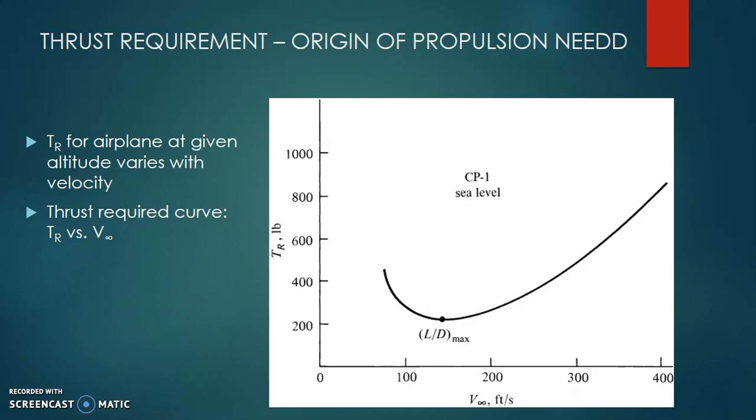So the excess lift actually causes it to go into a circular path, or to ensure that it doesn't go into a circular path, you have to adjust using your flaps and your ailerons. Therefore that additional lift, because of these high velocities, is not very optimally useful. But drag is always a penalizing drag. No matter what you do with lift, it says, boss, my job is to penalize you. With additional velocities, in the regime of higher velocities, drag increases. Hence, to match it, the thrust required keeps increasing.